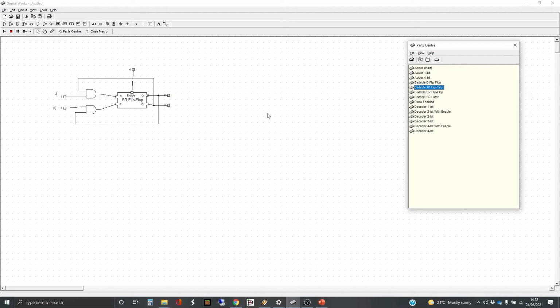The point that we're at is that we've just in this series done a thing called the D flip-flop, which is a basic memory cell which can take data in, and when the enable line has a 1 come into it, it will then actively remember the state of the D line, the data line. I want to talk about another version of the flip-flop, which builds on the SR flip-flop, the set reset, which is called a JK flip-flop.